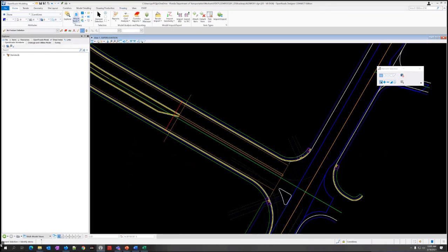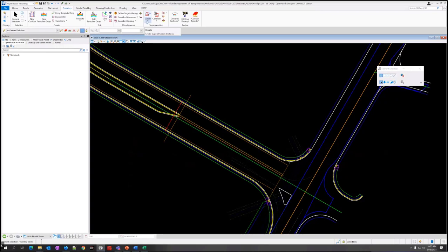So exercise 3.3, top of page 3-5. We're going to go to the corridors tab. And we're going over here. Most of the tools for this session are going to be in the super elevation section right here. So first thing, same logic. Usually you start from here for the first workflow. Create. Now if you click this drop down, there's 3 different options here.